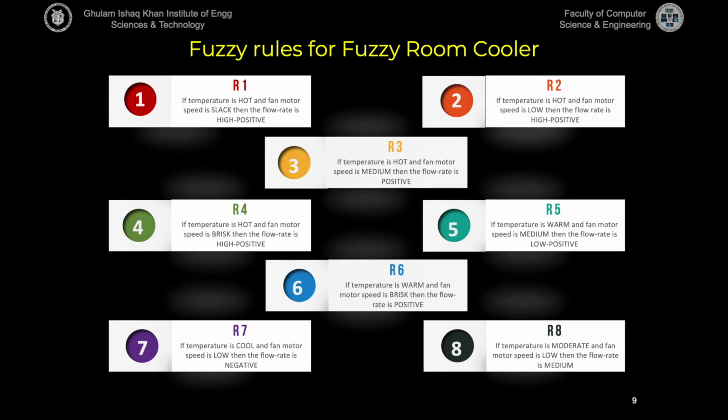Notice that if a situation occurs such that you cannot find the corresponding rule, then the system is going to fail clearly. Then the machine will not work, and hence one of the assumptions that we have used in the fuzzy logic control design, the assumption that the solution must exist, is violated. Since there is no rule for it, that means that no solution exists for it, and hence a fuzzy logic control system cannot be designed for it.